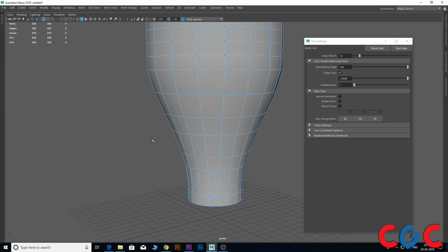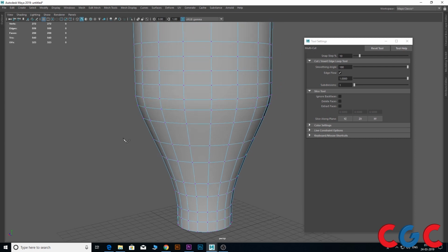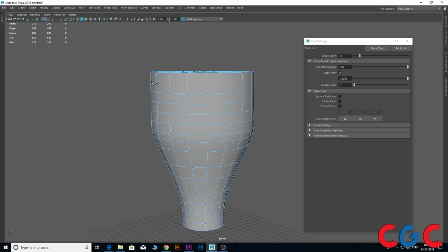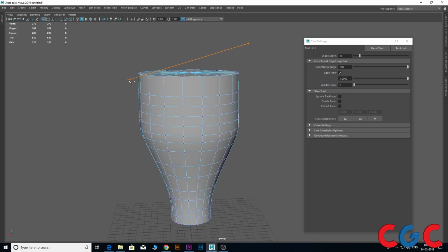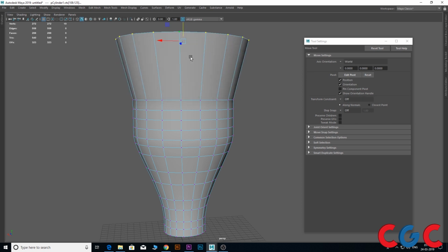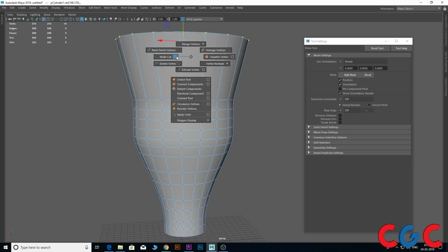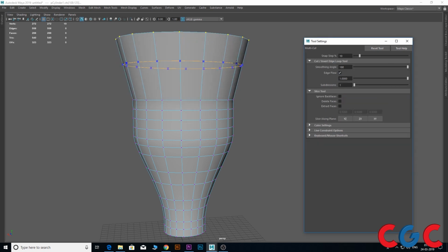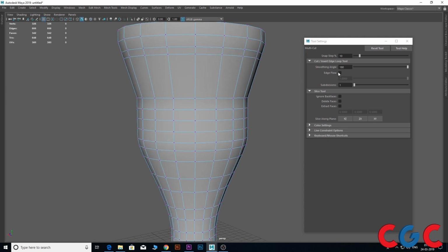Depending on my flow, the loop is getting applied. You can see over here, Multicut with the edge flow available. We can see an edge flow happening. But when I turn it off, there won't be any change. So this intensity you can increase or decrease.